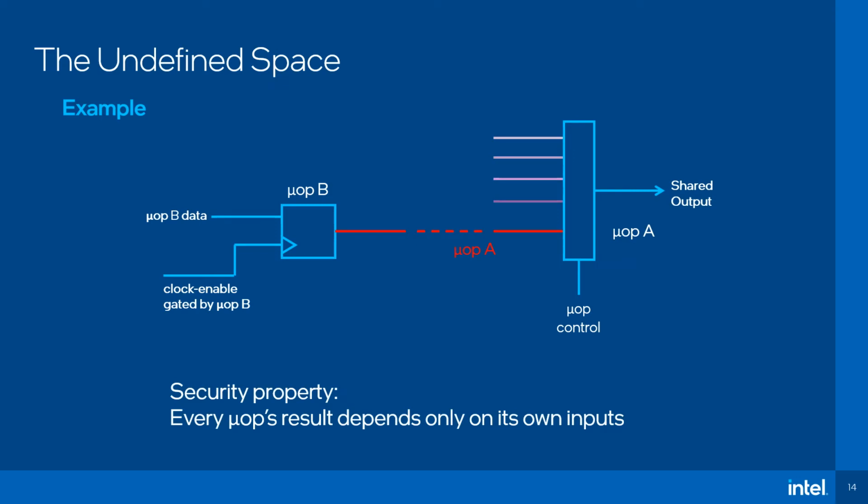We define the following security property. Every operation is dependent only on the input sources driven at the right pipe stage of the currently operating UOP. So it would not be possible to read information coming from a producer UOP sometime in the past that might hold secret information, whether it was left there a cycle ago or a million cycles ago.